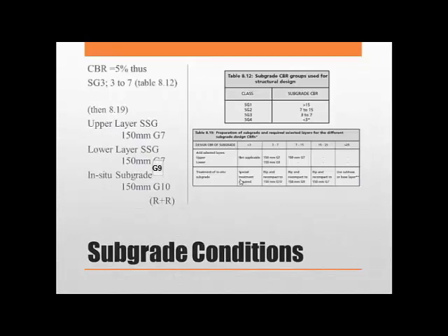Subgrade areas are delineated before construction as per Table 8.12. Subgrades with a CBR of less than 3 would require treatments such as chemical or mechanical stabilization, chemical modification, or the removal or addition of extra cover. Therefore, it will be classified to a group.